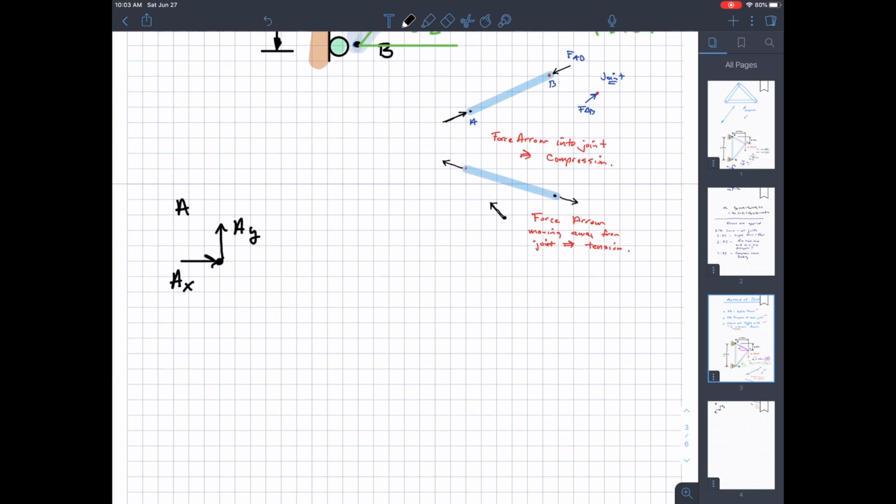I'm going to draw all of the member forces as if they were in compression. I'm not going to try to guess. I'm just going to always reference things in a certain direction. Now, I'm an electrical engineer, and when you solve circuit problems, you have to make assumptions about voltages and currents and which directions they flow. I do the same thing when I do that kind of analysis. I always just assume one thing and then let the signs of the mathematics tell me if I'm wrong. It's not being wrong, it's just a matter of how you interpret the direction of a positive force.